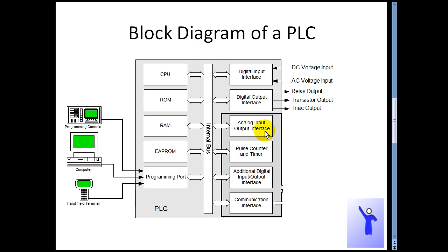An analog signal will probably be a number, a pressure, distance, temperature. An analog input will accept a signal as a voltage or current in a larger range. So it is not just 0 or 1, it is a value like 1, 2, 3, 4, 5, 6, 10, 20. So it can be anything in between.